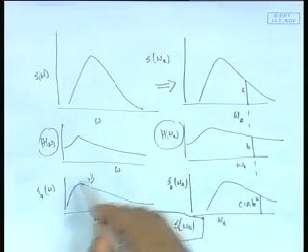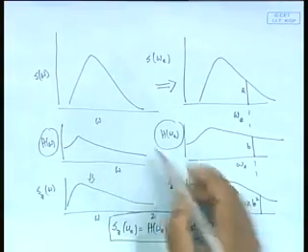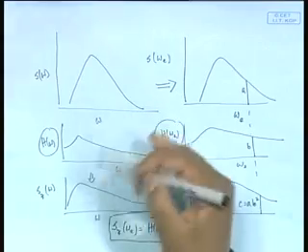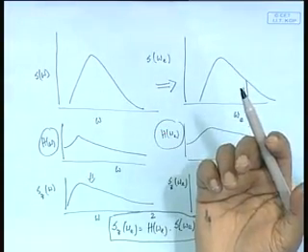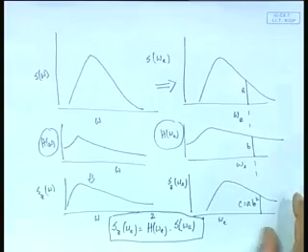Or supposing I find out a ship's behavior, how much it behaves in, say, a 50 meter long wave, 100 meter long wave, 200 meter long wave, over a range of lengths. I will plot them against some parameter here, which can be length or omega, and on this side output per unit amplitude. That is RAO. So, RAO is always that, we are calling it.